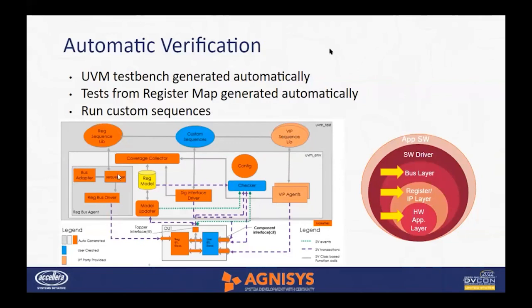Here, this snippet shows the verification environment generated by IDS-NG. We are targeting the bus layer, register IP layer, and hardware layer. IDS-NG automatically generates an IP verification environment from a golden specification and hooks up the user RTL with the IDS wrapper. The boxes represented in orange, gray, and light gray are components automatically generated by the tool, and the blue ones are user-defined RTL. The dotted line represents the SV transaction for event capturing at the checker.